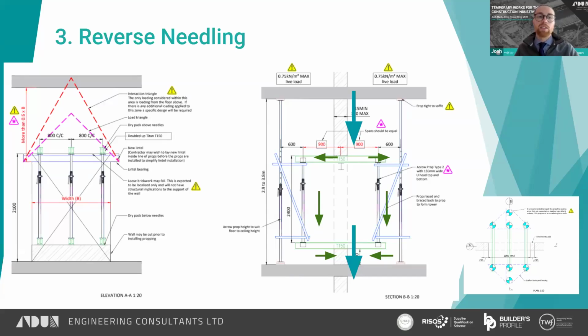But this reverse needling scheme is really quite helpful on the weaker floors or where you want to separate particular activities between floors so that there's no back propping going all the way down the structure and then limiting access and limiting site construction activities on those floors.